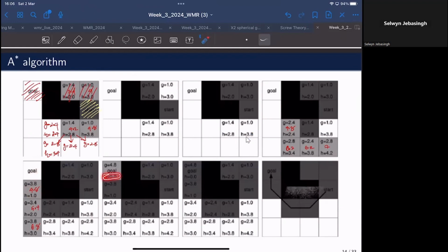And at the goal, the heuristic cost is 0 because the distance from the goal point to its own location is essentially 0. So now when you backtrack, which are the nodes that you have expanded? So you expanded this node, you expanded this node, then you expanded this node, and at the end you reach this node. So with that, you can essentially backtrack to find the path that you can actually follow that will yield you the path with lowest expected cost.